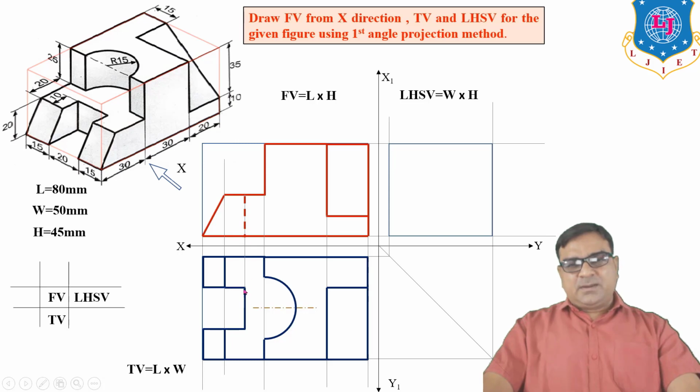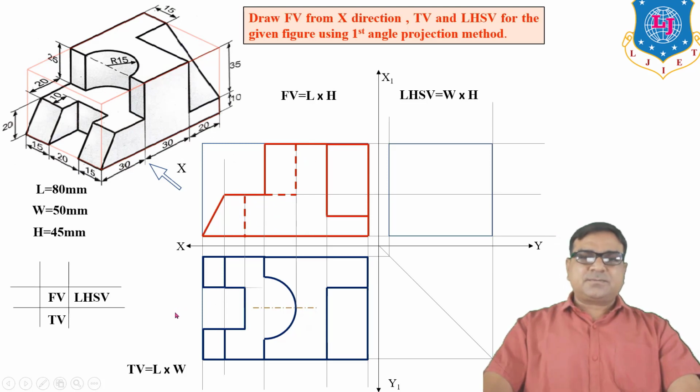The top view of that surface is here. Okay. So another, which line or which surface is hidden? The semicircle you cannot see from front view. So the end of radius, this surface, is represented by a hidden line, and from front view this surface is also here.